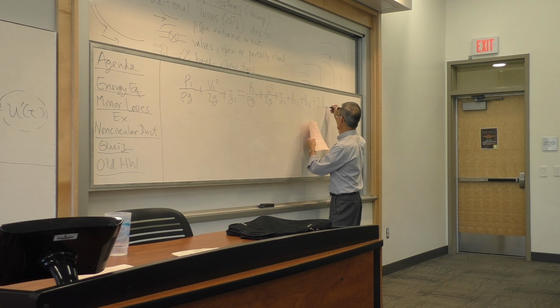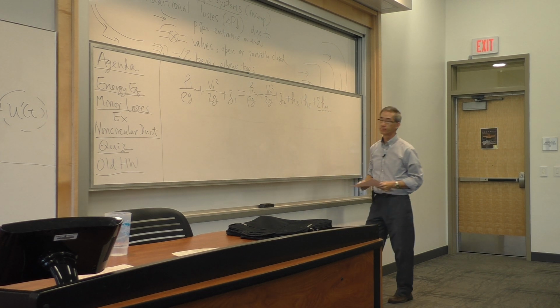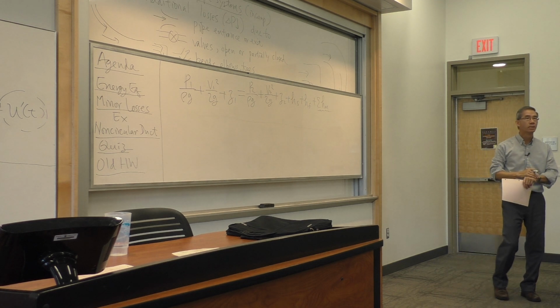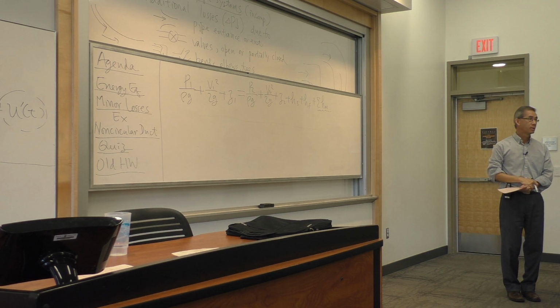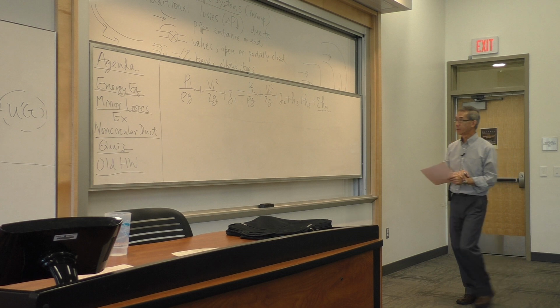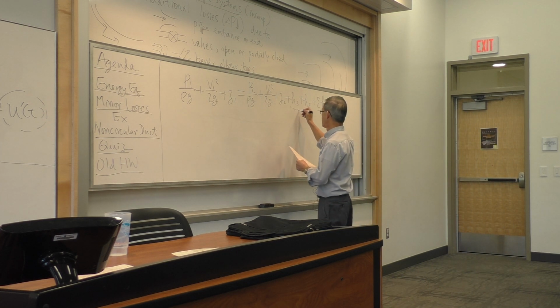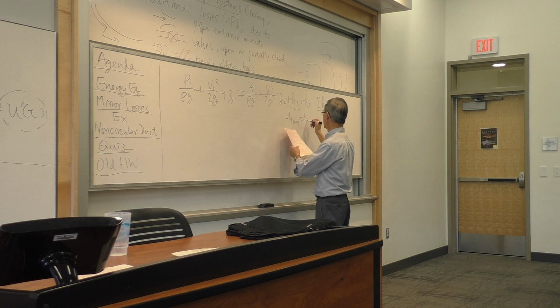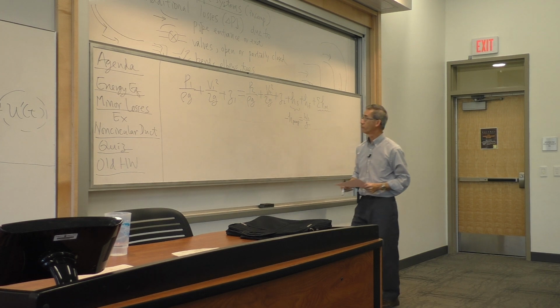I'm now adding a new term, which accounts for all those components that can increase my losses. And the summation sign, meaning I have to add them all up. And the shaft work, since this is a pump, is negative. And that sign is important to account for.